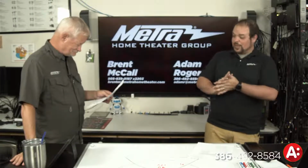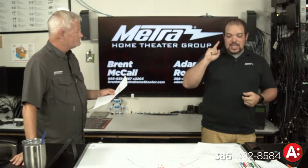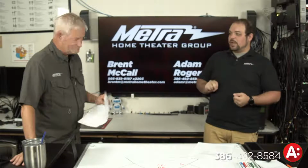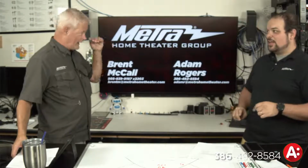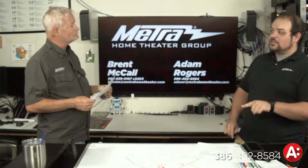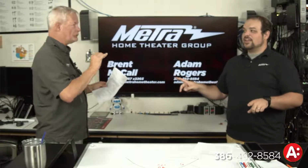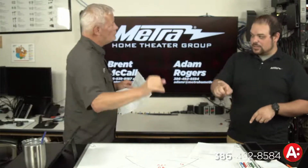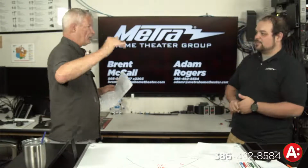So 4PPoE, and that gets to be a mouthful every once in a while, it uses all 4 twisted pairs for its power. Now, is it using alternative A? Yes, but no, because alternative A doesn't use 2 of the twisted pairs. My guess is it's using the format which is the differential. It uses the differential, but on all pairs, so we can carry much more voltage down the pipe.